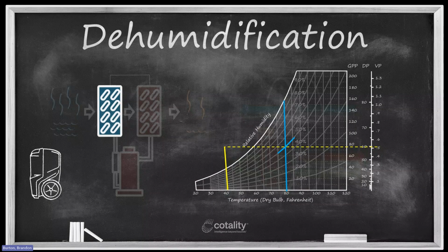And that's where the limitation on even low-grain refrigerants really starts to kick in, is when we get into these defrosting cycles. And you've probably run into this. You go in to monitor your dehumidification systems, you take your thermal hygrometer, you take a temperature and humidity reading, and you say, you know what, this doesn't make any sense. The air coming out of my refrigerant dehumidifier is cool and very humid. Right? If any air is coming out at all, depending on the type that it is. So that's a very severe limitation on the refrigerant dehumidification system.